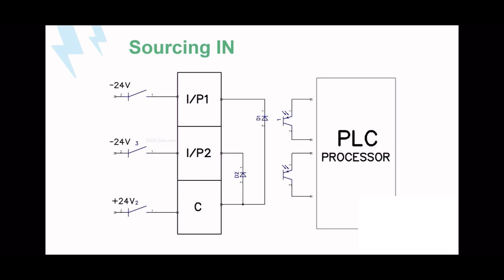For providing the forward biasing, you need to connect the P region as positive and the N region as negative. Here you can see the C, that means the common, and there is input 1 and input 2. In the case of the common, the diodes' P regions are connected, so you can connect the positive supply through this C.